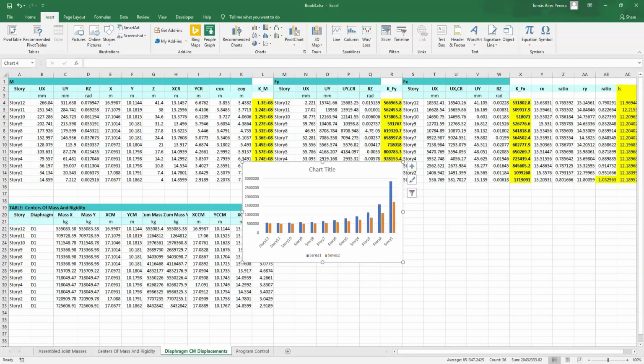However, there is no fundamental aspect visible that would point to an unnecessary or exaggerated change in stiffness beyond what is normal for a wall or frame building. In wall structures specifically, this is more noticeable. Looking at these two charts, we can clearly conclude that from the standpoint of story-to-story stiffness variation, lateral bending stiffness per story, this is not a reason to disqualify the structure as regular in height.